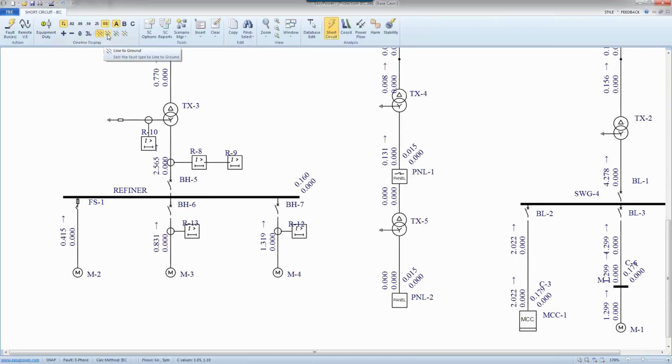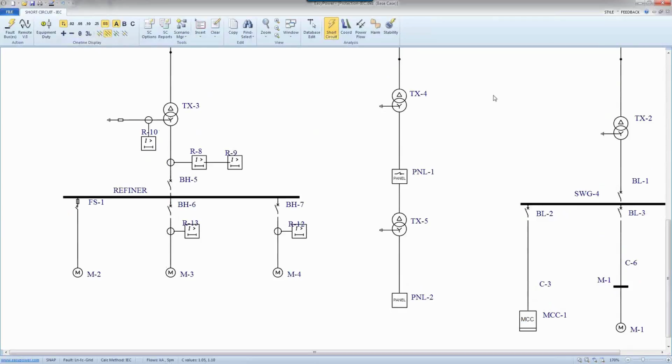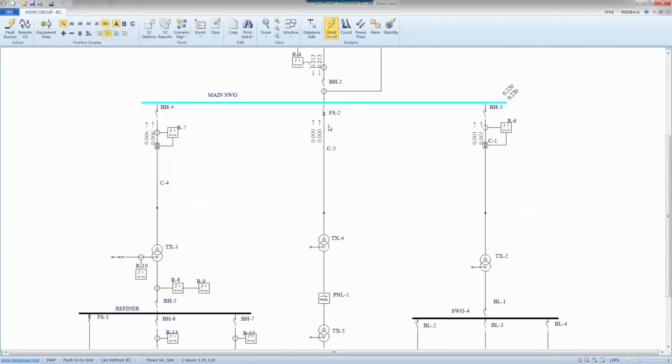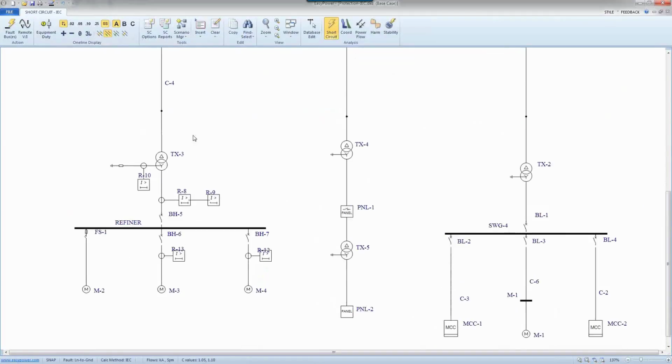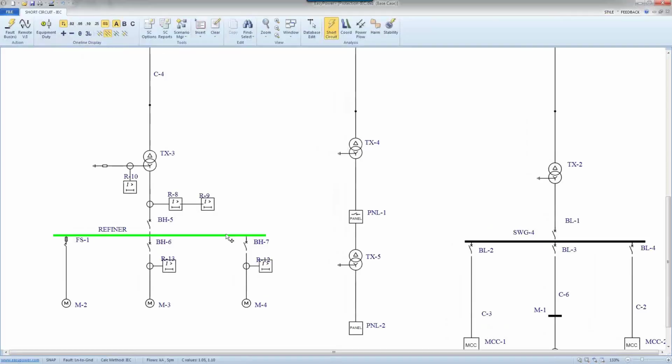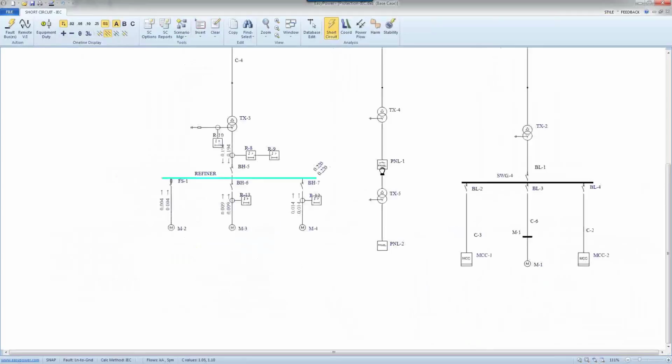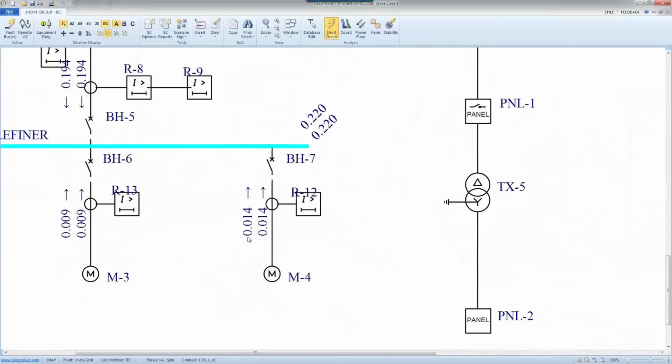for unbalanced faults. So if you have an unbalanced fault here, and I change it from 3-phase to single line to ground, so I'm going to fault this point and come back and look at the steady state values here for the motors. Let me just fault this point so that it's easier to focus, to zoom in here. So, well, I just violated the rule that I set up here. This guy has a steady state contribution. So the addition to that statement is that for balanced faults, we cut off motor contribution for a steady state once Cmax is chosen.